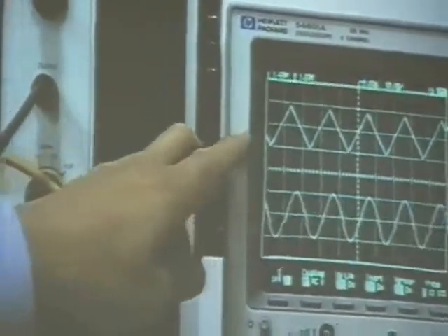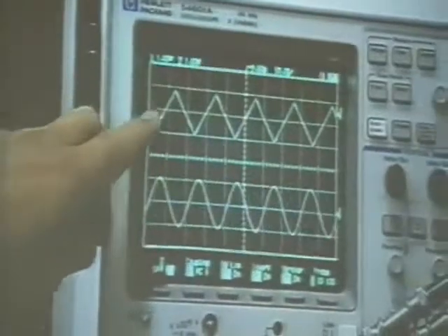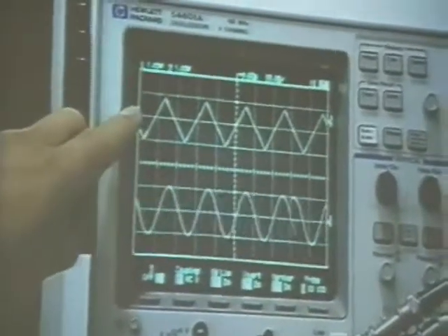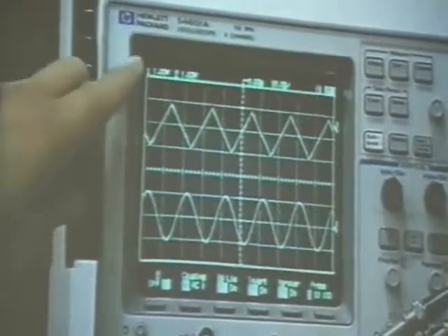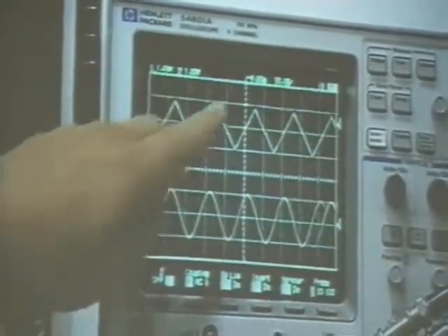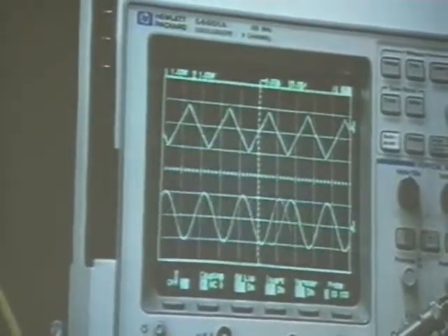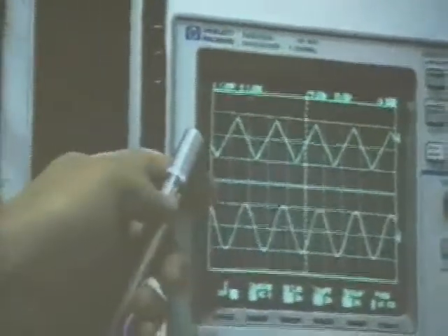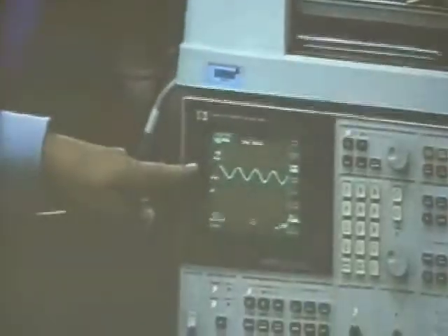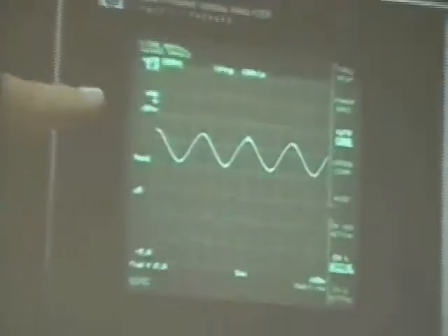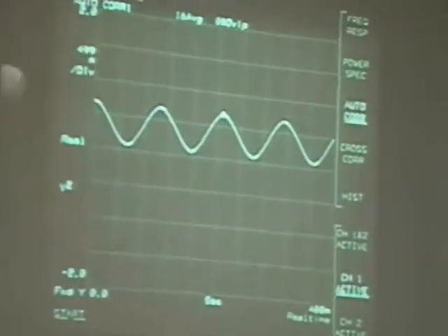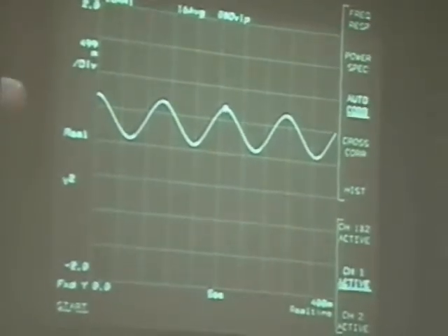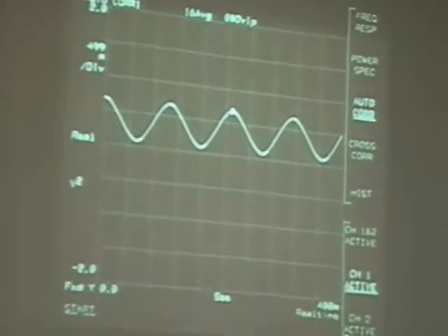The triangular wave, as you see, has a period, of course, for 10 hertz, which is 0.1 second. And this really consists of many sine waves, so close to a sine wave. So you expect the output, which is the autocorrelation function here, to again be the cosine wave, or you can just generally say the harmonic function again. Okay? So that's what you see here.